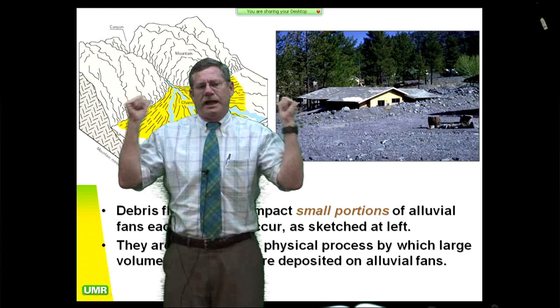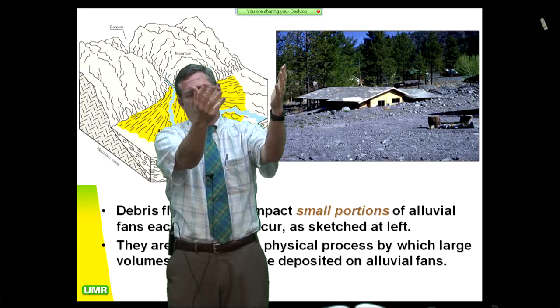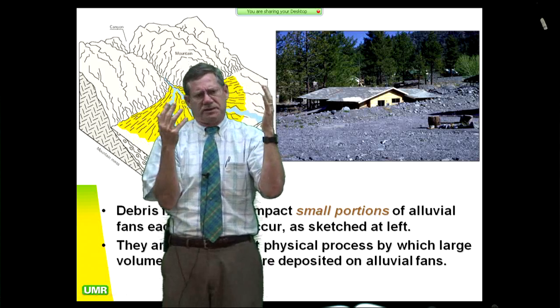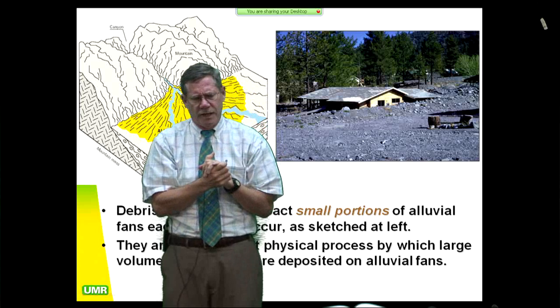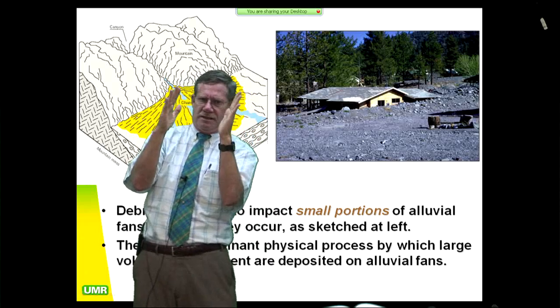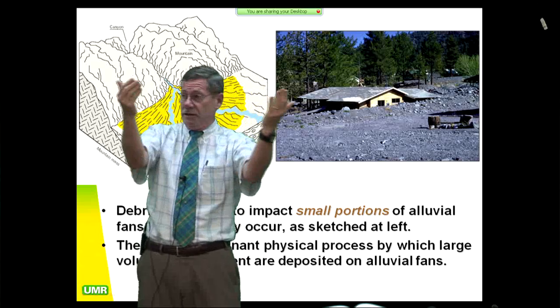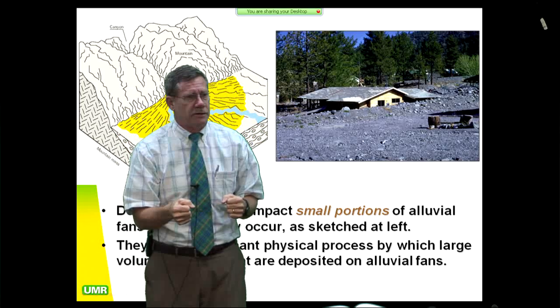And they couldn't get out of their bedroom because the next door neighbor's house had crashed into their house in the middle of the night because of the debris flow, and the next door neighbors weren't home. And the house got tweaked in simple shear like this. And when you have simple shear to the framing, you can't open the windows and you can't open the doors.